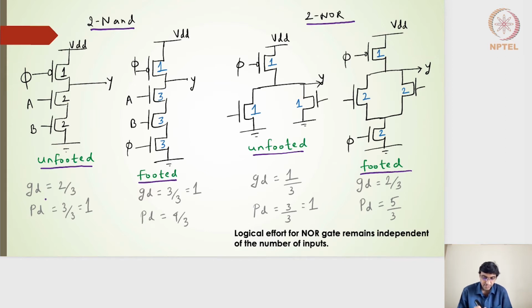So my logical effort for going down will be nothing but 2 and this one will see a benchmark inverter of 2:1. So my logical effort will be 2 for the input capacitance here divided by the 2:1 inverter will give me an input capacitance of 3. Parasitics will be nothing but 2 plus 1 here. The output node sees a capacitance of 3 and then divided by the 2:1 inverter's capacitance of 3. So the parasitics will be nothing but 1.